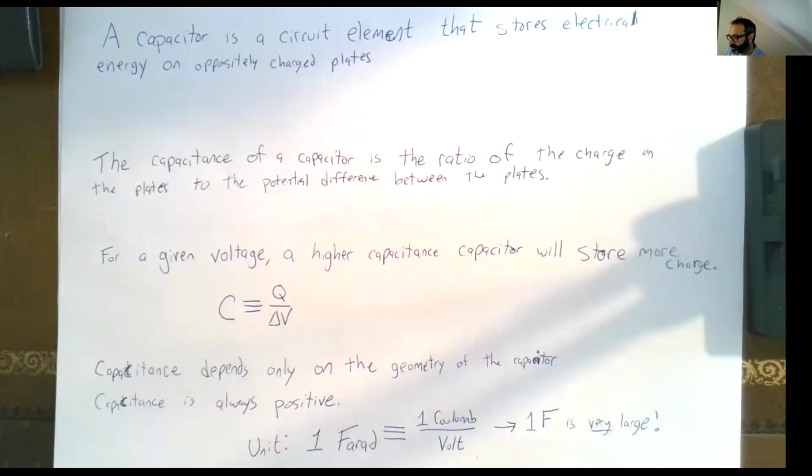In practice, in a circuit, big parallel plates are going to take up a lot of room. So you roll up the parallel plates into a cylinder, and that doesn't change the capacitance that much. That's why when we see capacitors in circuits, they're usually cylindrical shaped. They're those parallel plates that are rolled up. There are a few other configurations, but by far the most common and the easiest to calculate with are the parallel plates.